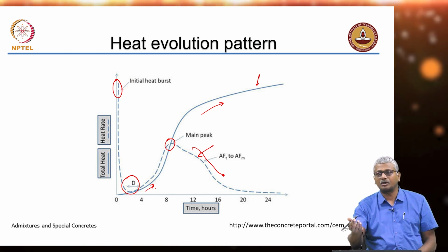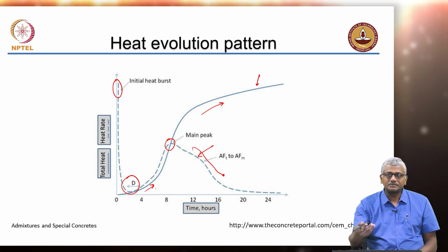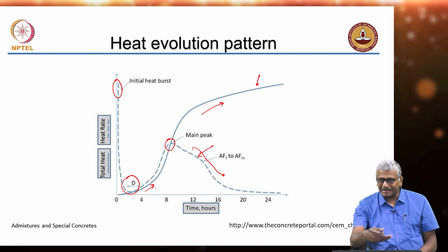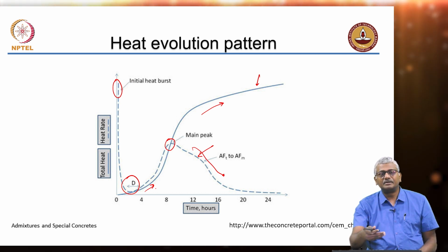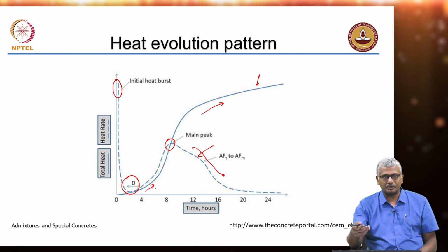Workability, we need concrete workability at that time. If the cement starts setting and hardening, obviously we can't get workability from the concrete. So, this dormant period dictates the time that we have with the concrete, or we sometimes call it the open time, workable time of the concrete.